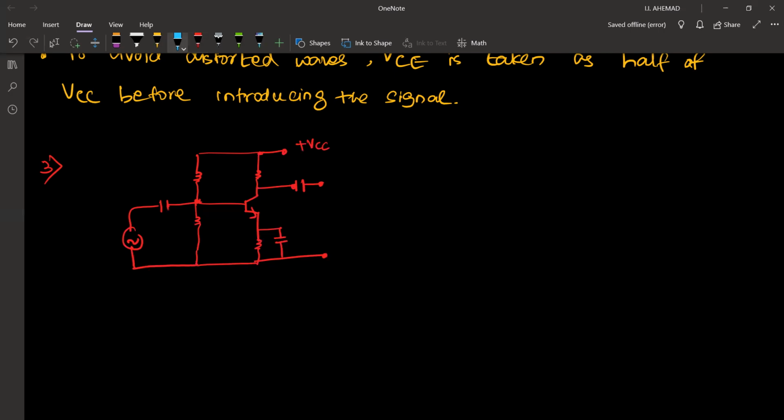So this is the RC resistor. This is resistor RE. This is RB and this is R. C1, C2, and C3. In the previous diagram, I think we didn't have this resistor. It is not an issue, right? You know what the reason is. We can bias by base resistor biasing, or also by potential divider biasing. Here, let's look at potential divider biasing.